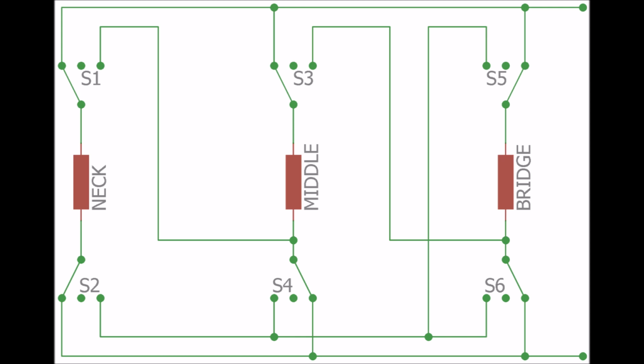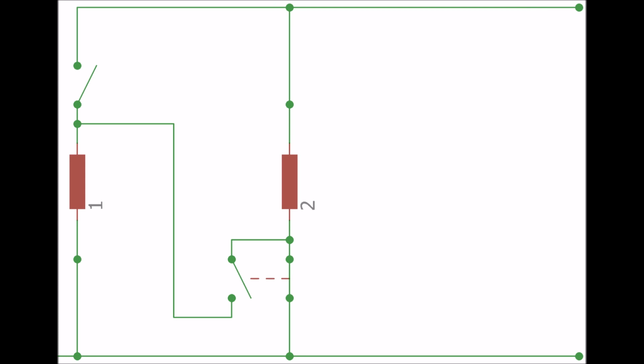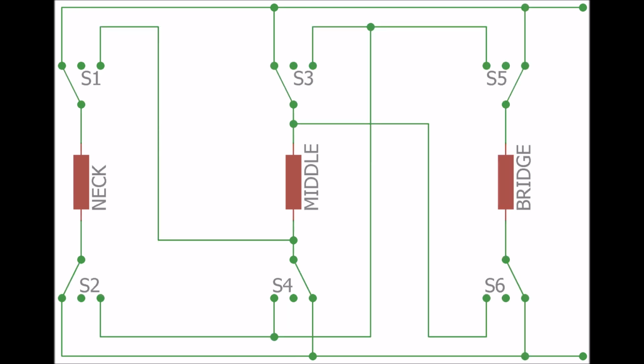Or, continue with the apparent solution postulate, that is, to make a series connection state true, the state of only one switch needs to be true. Thus, we can also try to remove S6 from the junction on the parallel to series path, by making S6 a binary operation to connect the bridge pickup to the middle pickup in series, and make S3 and S6 function as a logic AND, for the same lead of the bridge pickup to connect to the bus.